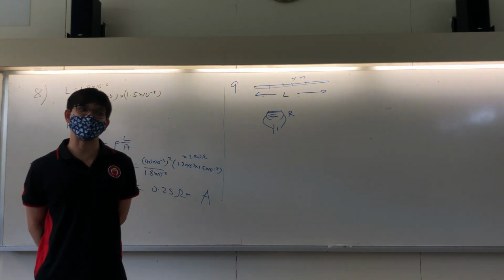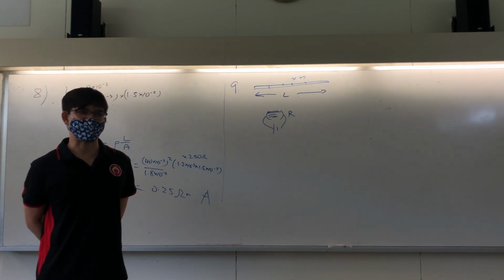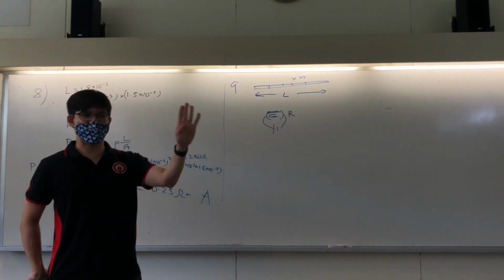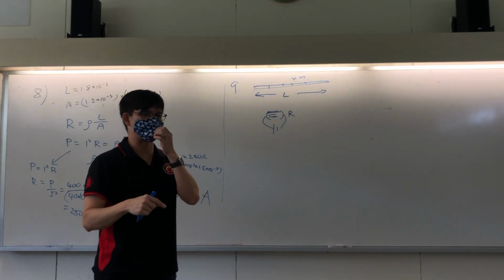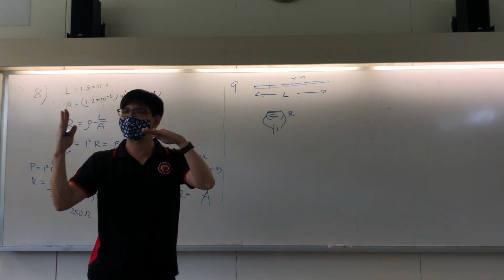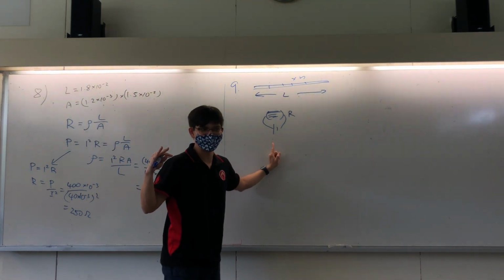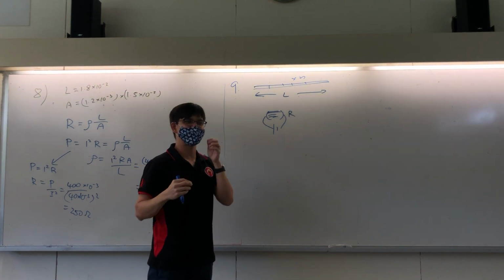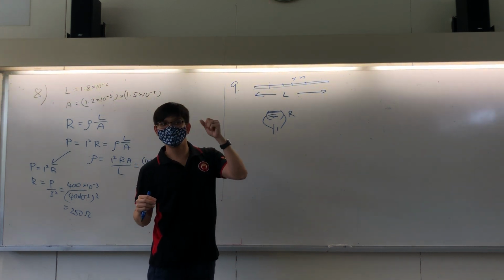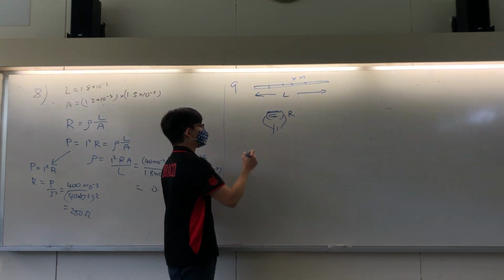So actually, it doesn't matter whether they're insulated or not. Even if they're not insulated, it's as if they are insulated, because the current will just keep flowing through them in the length direction. There's no reason for the current to flow between strands because there's no potential difference between the strands at each point. The potential difference is between the left and the right side from the battery. So they don't need to be insulated within the bundle. All good? Yep. So, these guys are in parallel.